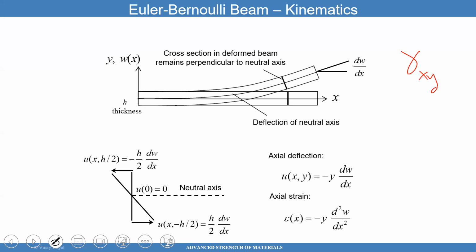If the initial angle is 90 degrees and during deformation the angle is still 90 degrees, what is the shear strain? 0. Do you have a different answer? Who else is saying 0? So is this shear strain 0? Is that what we're saying? How many vote that if the angle change is 0, the shear strain gamma xy is 0? What is the definition of shear strain?